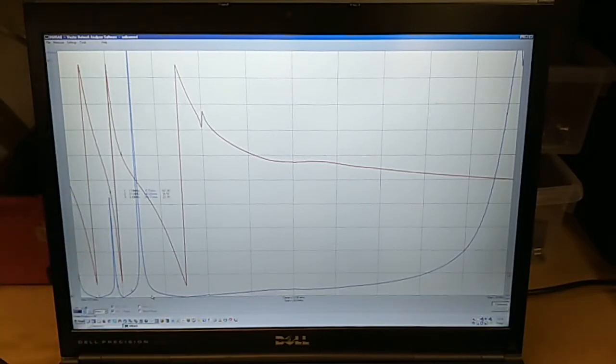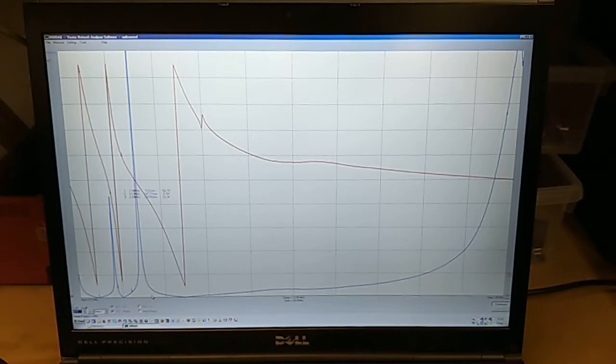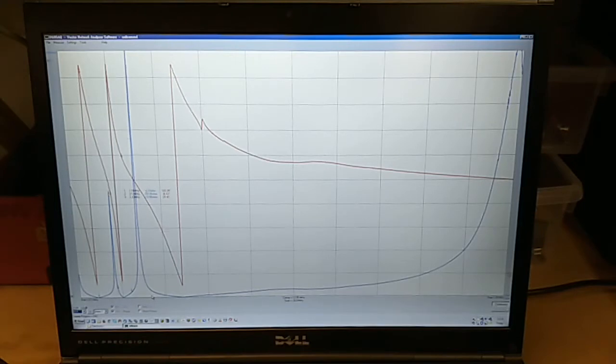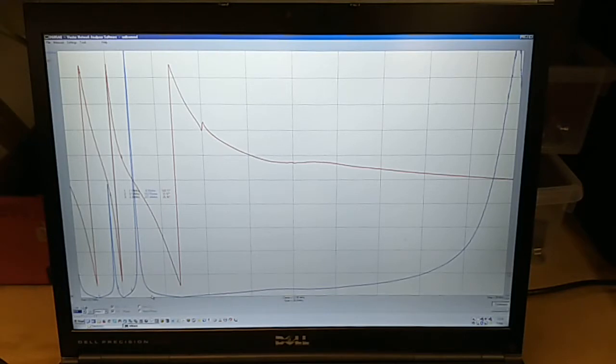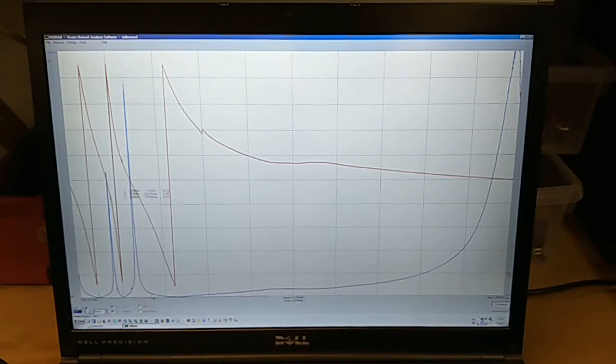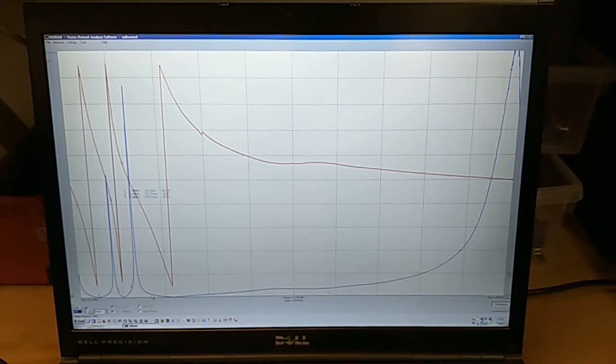We saw this before in part 1 of the transference. This hasn't changed, and it wouldn't change because the tank capacitor isn't being adjusted. We're coming down to around about 600 picofarads. We'll be coming into that optimum balance point soon, where the impedances are matched.